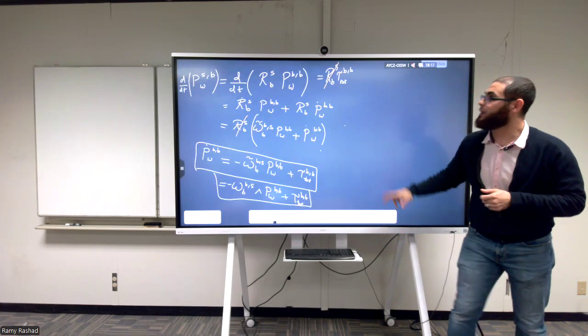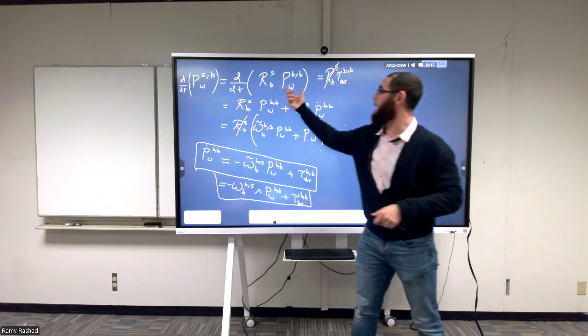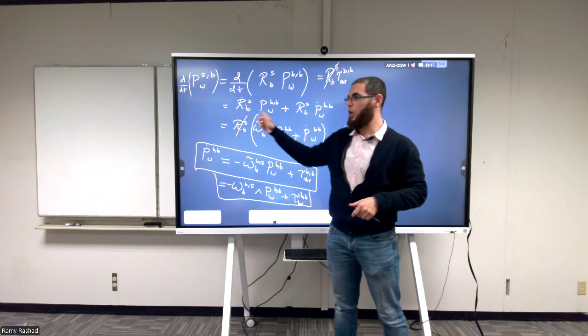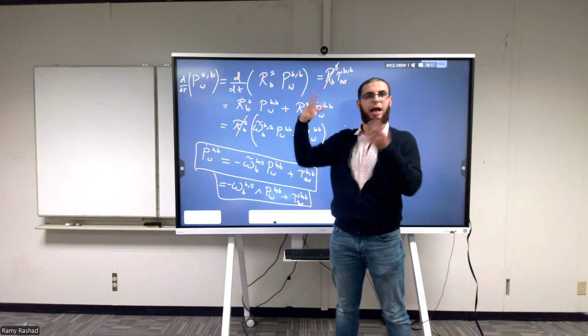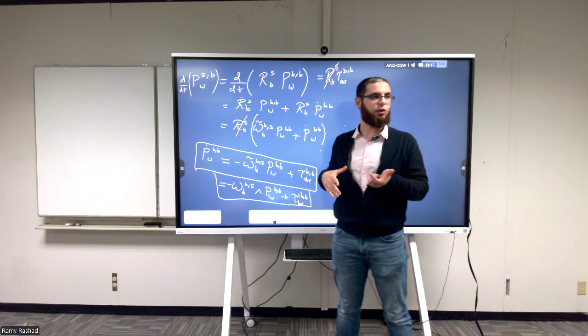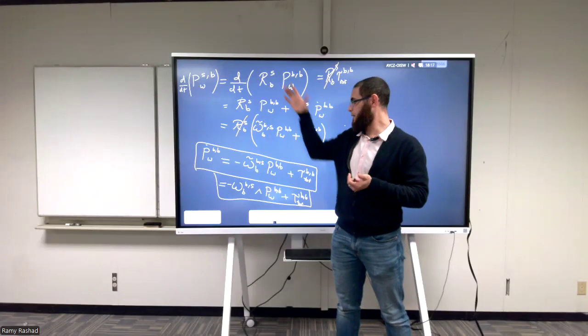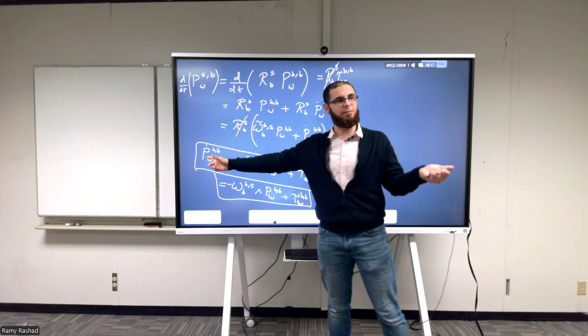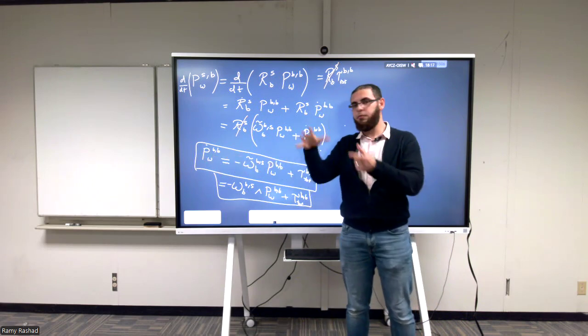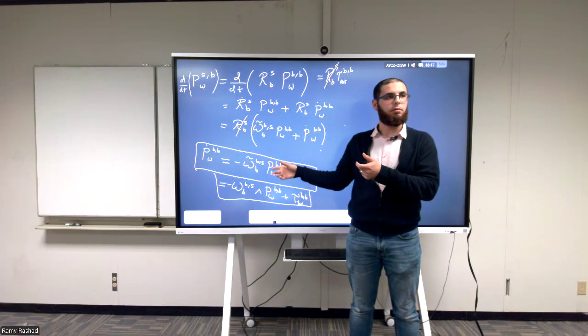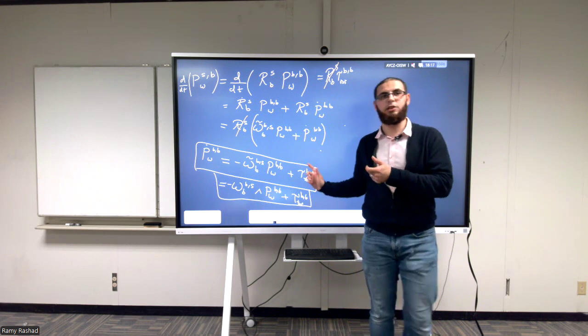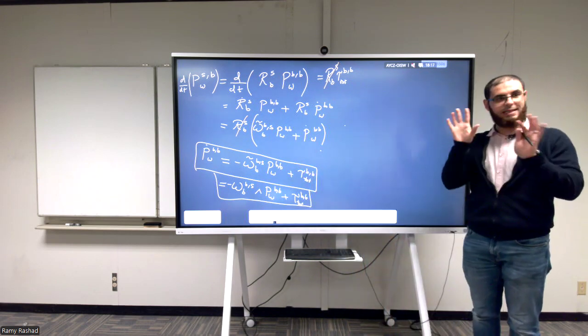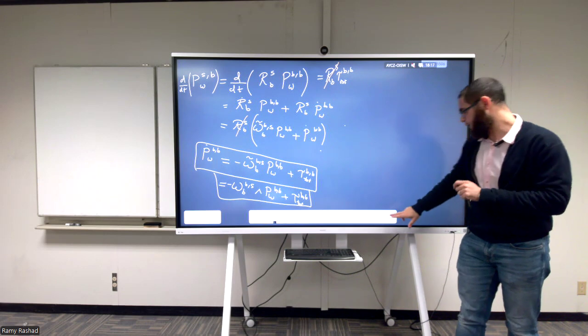And then later, when we differentiate this, we're going to need to take the rate of change of the adjoint, so we're going to need to look at some math. And in the end, we're going to get something very similar to this: the rate of change of the generalized momentum will be equal to some fictitious forces plus the applied wrenches in the body frame. Okay, so this is the sketch. Now let's do it very quickly.